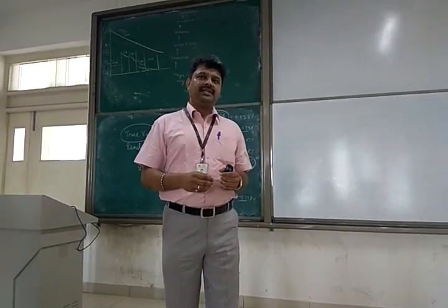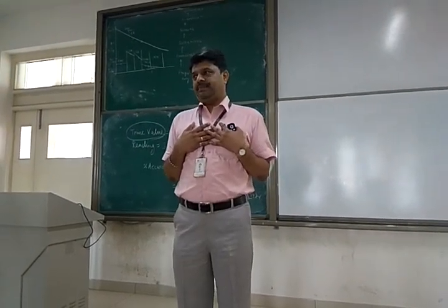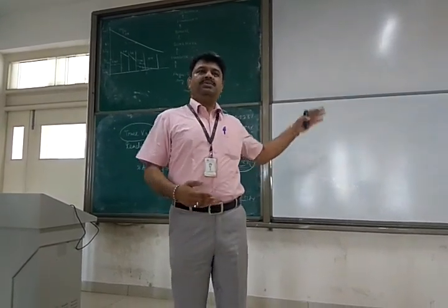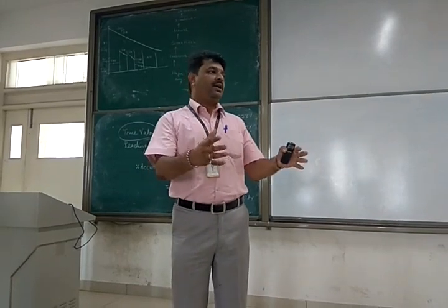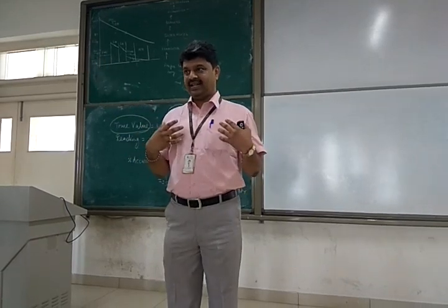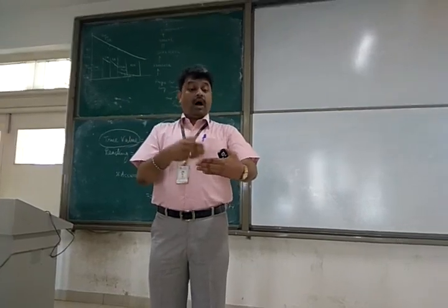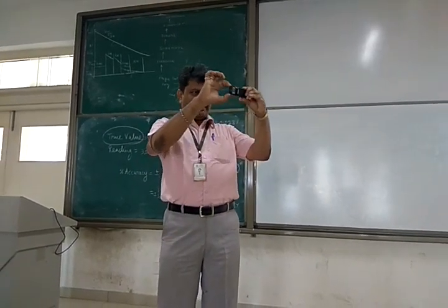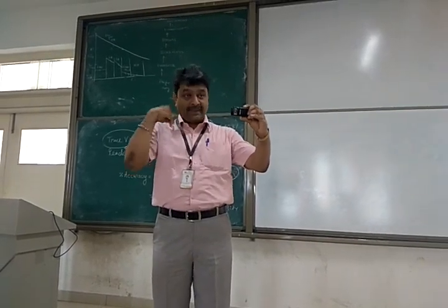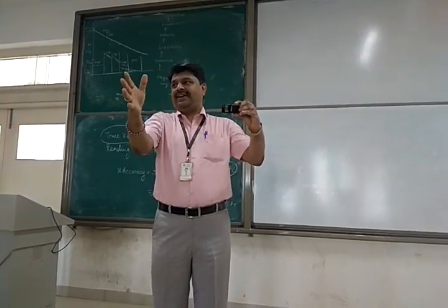And tolerance is the maximum amount of deviation I can tolerate. If you cross that, then I will have some difficulty in meeting the functional requirement. That is tolerance. I know such problems will come during manufacturing. I'm a designer, so I foresee the manufacturing difficulties and then assign how much. This is supposed to be 25 mm, but plus or minus 0.2 mm is alright due to manufacturing. I am assigning the maximum permissible error that I can tolerate.